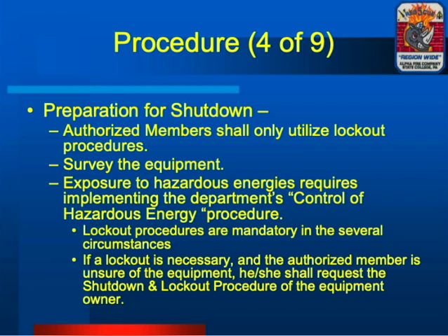And then lockout procedures are mandatory in several circumstances. So this is when you really need to complete a lockout device, or really kind of get into it and actually do some work. So whenever a machine guard has been removed, whenever safety interlocks have been disabled, when operations are required inside of an energized electrical panel, whenever a person is entrapped or entangled in energized equipment. Remember that may involve our rescue operations. And again, when we say energized equipment, that may mean any sort of energy that machine operates with. So it may be electrical and hydraulic, or maybe electrical, hydraulic, and pneumatic.